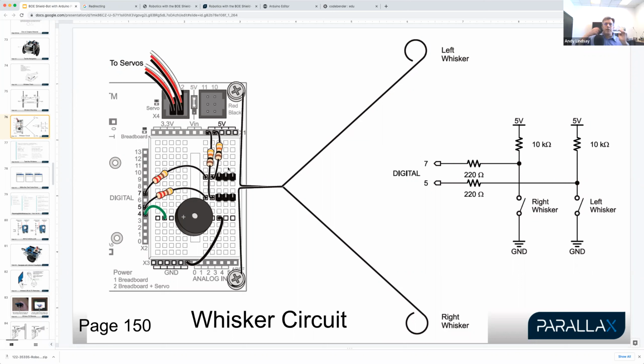Okay. So what's happening here is that the whisker is connected to chassis ground. So the little plated holes that the screw goes through eventually make their way electrically to the negative terminal of the battery pack and the ground terminal of the USB cable if it's connected. So this is a common ground, and it's considered to be 0 volts.